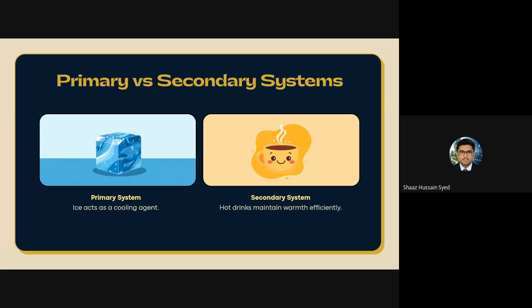a valve pit, and from there you take the connection to your ETS room, that is the energy transfer station room. From there, they will monitor their supply temperature, their return temperature, and the flow that you are consuming. That is the basis for them to measure the performance and bill you.